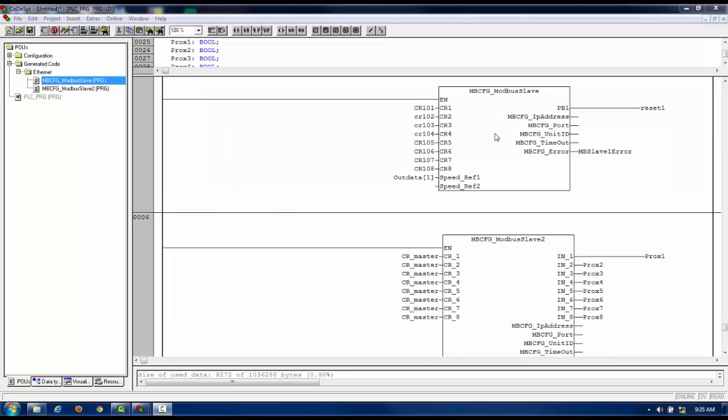So now you can see I have the program being called here. Like I said, I just went ahead and put in the variable names on the input-output side, writing and reading information to and from the slave device. These are your inputs over here. By the way, you get information that can be valuable, obviously here, this Modbus slave error information. We can put variables in here as far as changing input information with regards to the IP address of the device, port settings, and so forth.